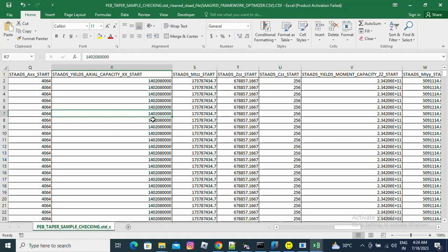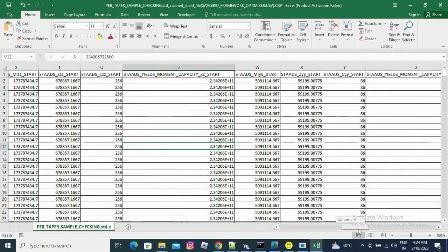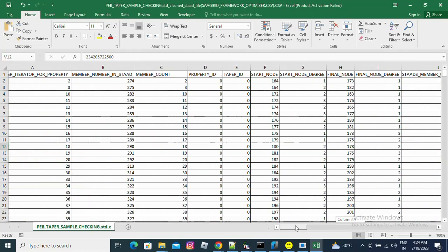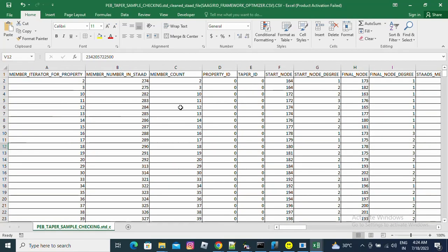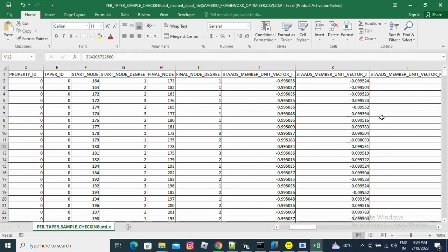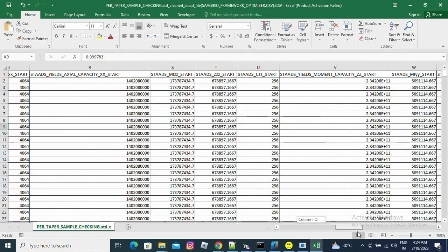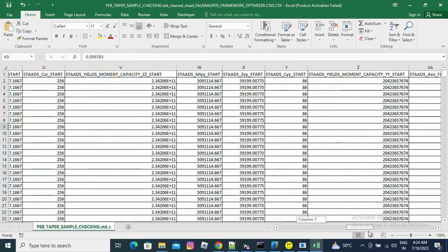Even if the server data are not found, it has the calculation within itself. It can calculate the moment of inertia of the sections. It has its own database to grab the data from the section profiles, and it prepares all the members' data for all the members. It parallelly writes the member ID, its taper properties, the start point, start depth, end depth. For every member it reports the nature of its depth and the nature of its valency.